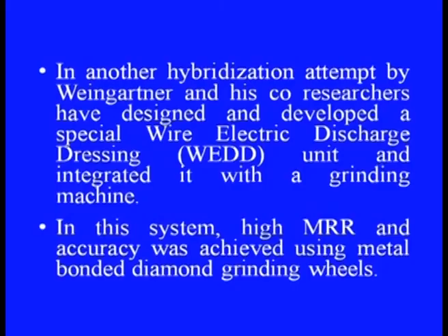Some studies also suggest that in WEDM, low conductivity of the dielectric should be incorporated for discharge sparks to take place. It was found that an AC pulse generator and low conducting dielectric provide better surfaces with reduced surface cracks and residual stresses.